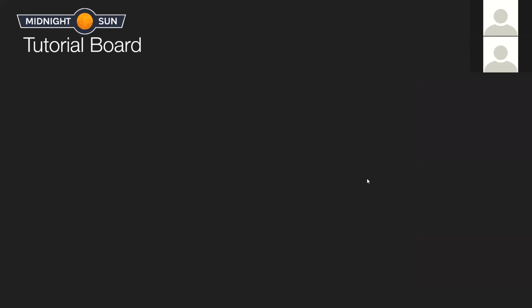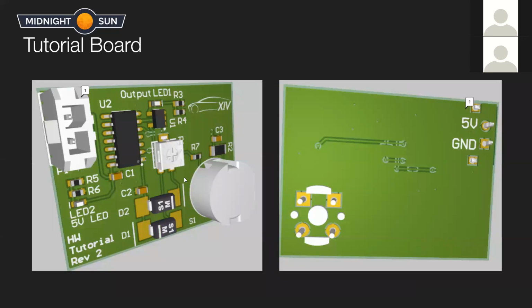If you take a look at some of the boards, there's a couple other things to notice. The first is the placement of connectors. You generally want to try and have your connectors on the edge of the board. You're not going to want to put your connector right in the center. You also want to orient the way of the plug, because if the plug is on the other side, it can get hard to plug into the connectors. So that's another thing you want to consider with the layout.